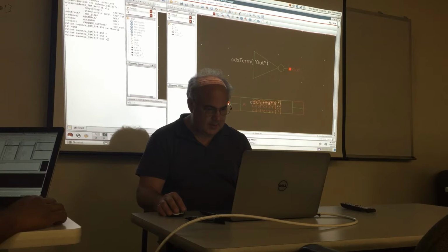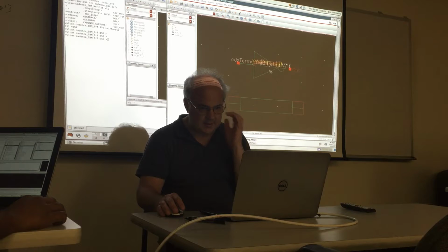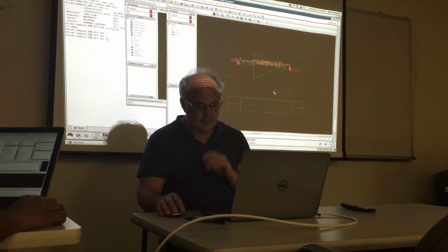But you just use the same schematic commands. You just do M for move, and then you can draw wires. They're not wires, they're actually just graphical symbols in this case. I think you double click to end it. And then again, don't delete these, just move them up. That CDS name is the name of the cell. That'll show inverter 1X, or in this case, it'll show test. Okay, and once you have that, these guys you can just get rid of.